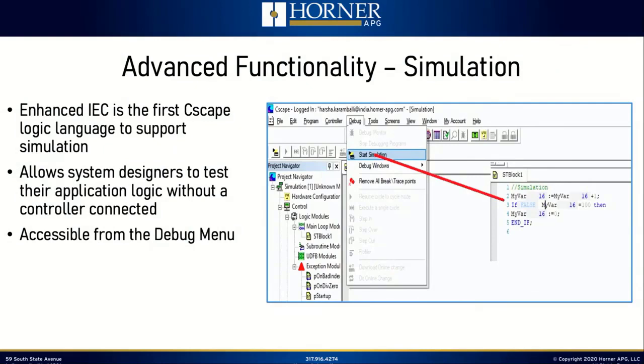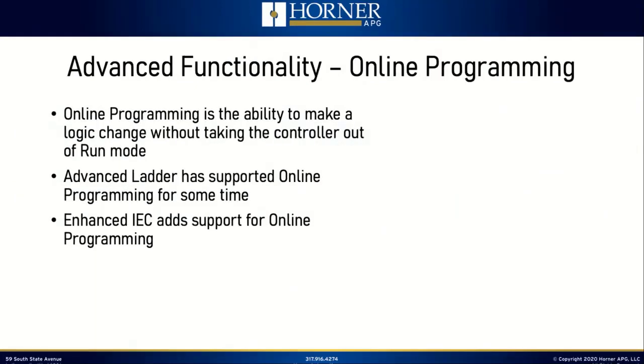The next thing we want to talk about is online programming. So online programming, effectively, is the ability to make a logic change, sometimes called an online change, without taking the controller out of run mode. Okay, so that's what online programming is. And many PLCs have supported online programming for years.